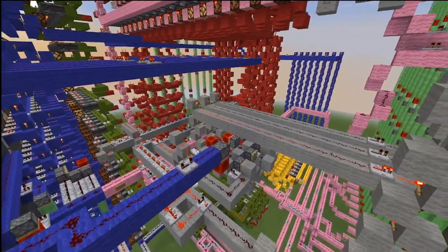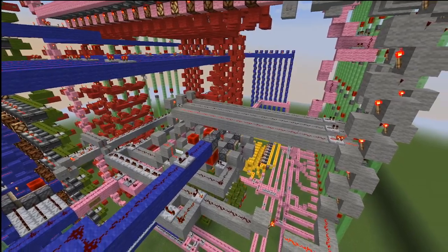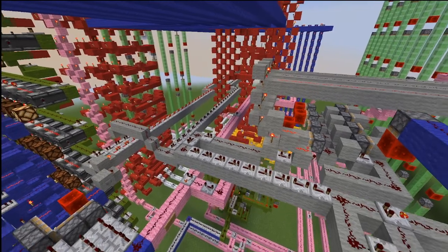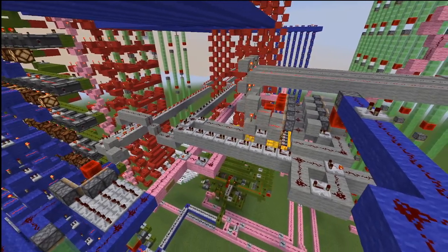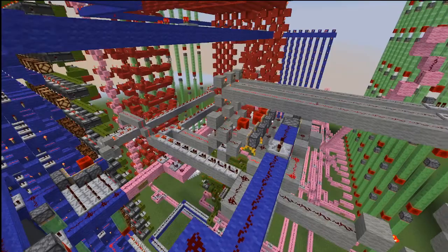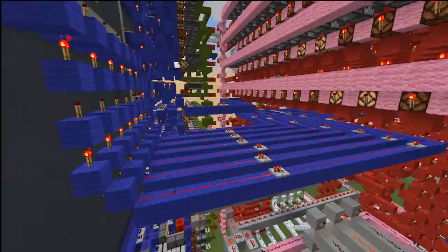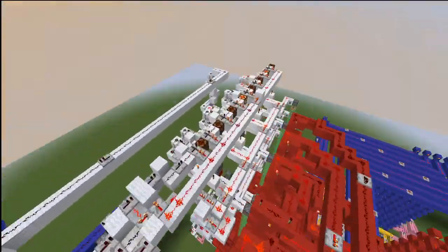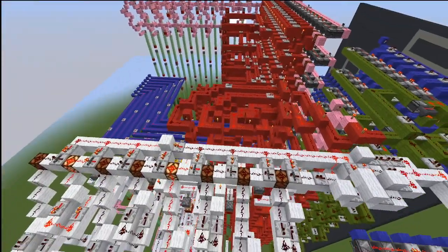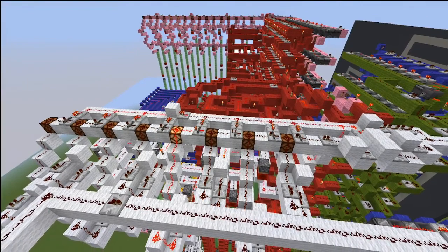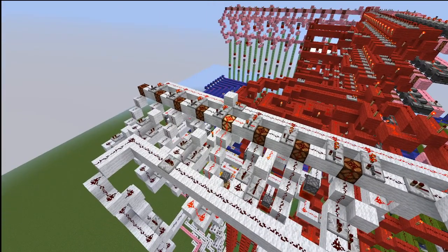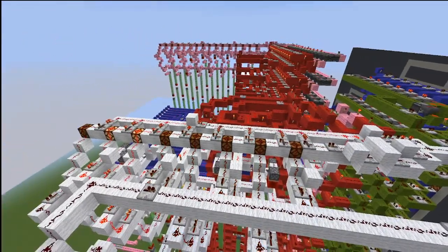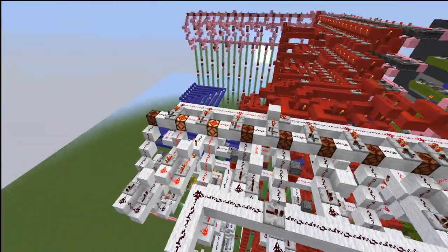Anyway, we're about to start the macro instruction when this clock pulse comes through for no operation. It's admittedly a very boring one, but it's important that you have a no operation. It's very fundamental. So this is going to read from the program counter. It should read an 8. And there we go. And that's because the program counter was set to 8. And then it's going to select from prom line 8, which is going to give us our instructions for no operation, which it just did.